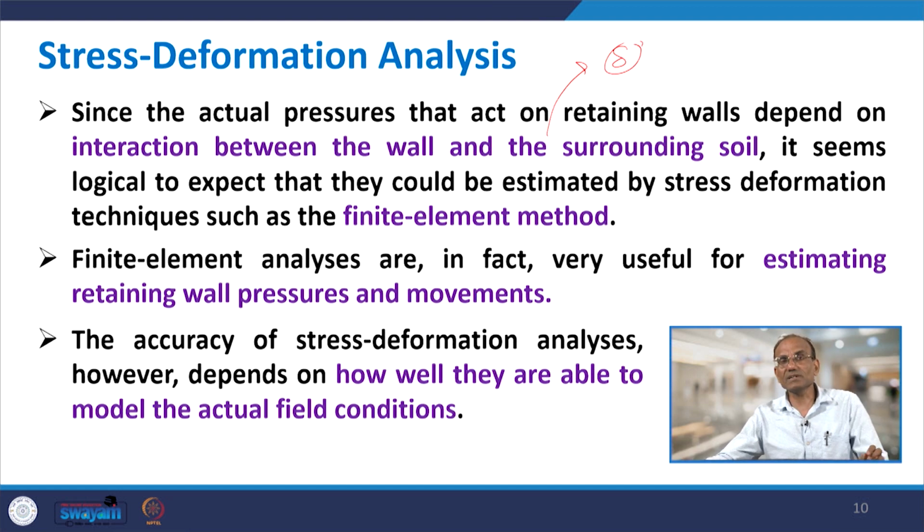It seems logical to expect that they could be estimated by stress deformation techniques such as the finite element method. Finite element analyses are in fact very useful for estimating retaining wall pressures and movements. So, the finite element analysis is used for stress deformation analysis, and here we can calculate wall pressure as well as movement. I mean, that means basically deformation.